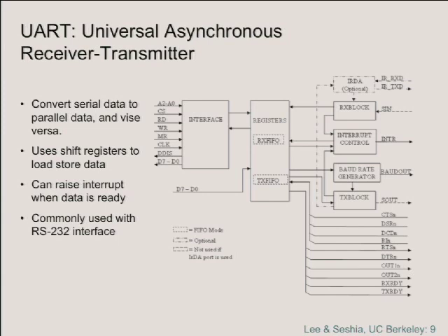But the key is you've got serial lines, which are shown here. Here's the serial out, and here's the serial in. Okay, so this is the hardware that, as soon as it sees the start bit, starts latching. And once it's latched 8 values, it sticks those in a register. Here's a device that hangs off the bus. When it sees its address, it asserts the value of that register on the bus.